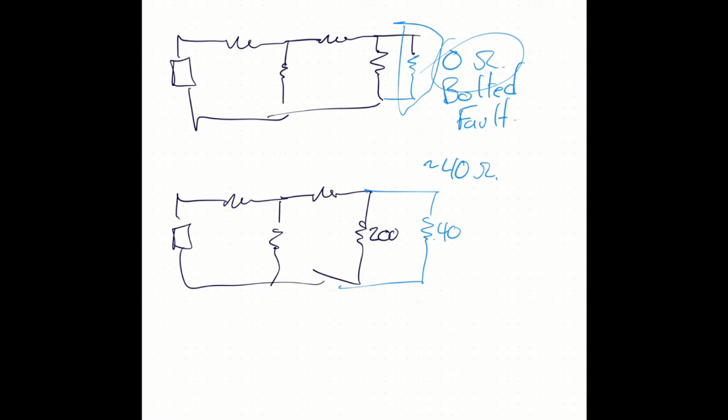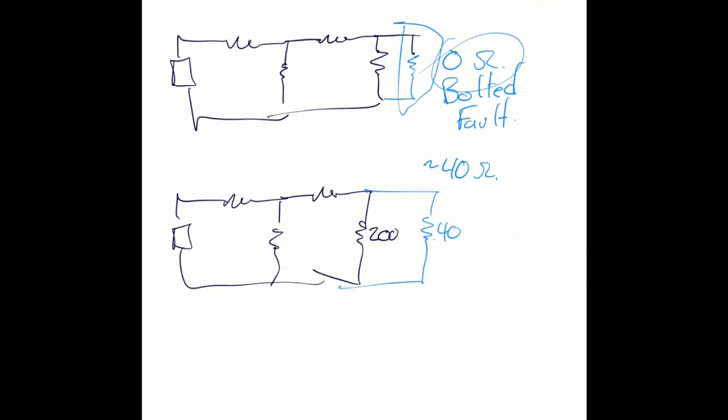The other place where you'll find this is if somebody made a big uh-oh and ended up buck phasing something. Like they tied a red to a white phase and then somebody closes a switch. And all of a sudden you have this phase-to-phase fault with no impedance on it at all. Really nice and solid connection. Out in the wild where you get tree branches and squirrels and birds and things, or tracking, you'll often see different levels of impedance, sometimes up to about 40 ohms.